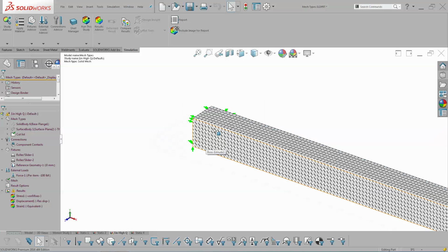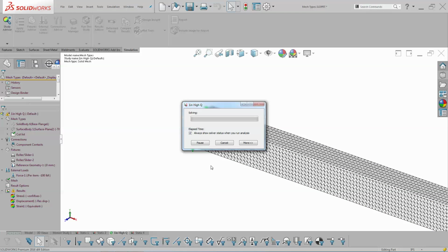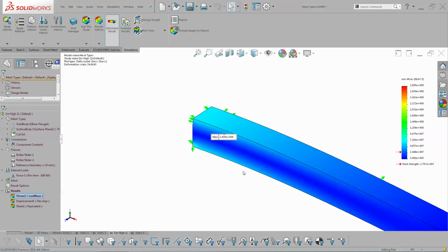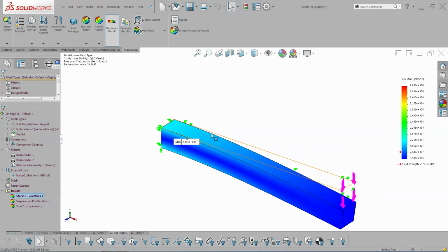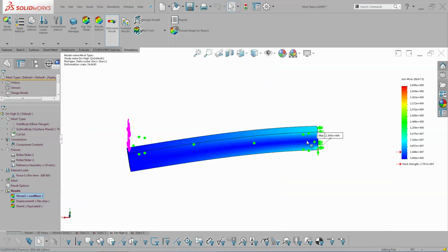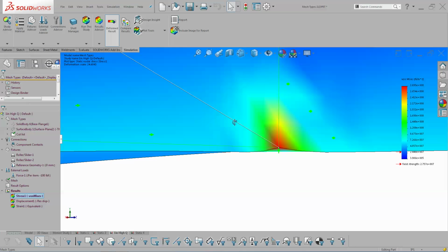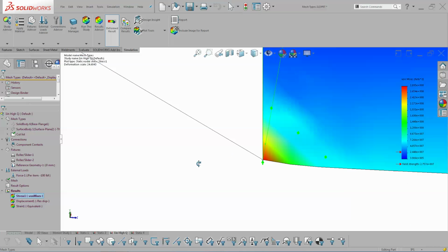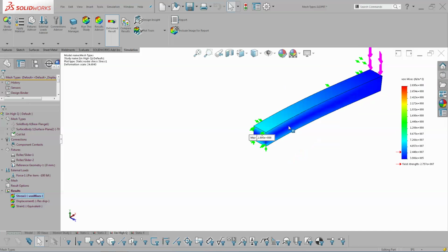All right. Now if you take a look at this, something is weird, right? Most of the part is blue, and yet the scale is going off the chart here. What's happening is right here in this corner, we're getting a stress singularity. All right? So two ways you can look at this. One is to attempt to remodel this part. Maybe this is a simplification we've made on our model, and maybe there's some detail we're missing there, maybe a fillet or a load-bearing piece, right? That's going to take some of that force and transition it smoothly.